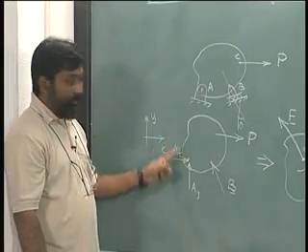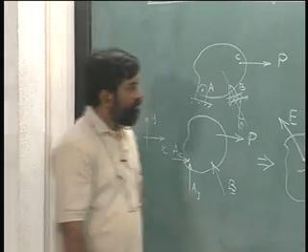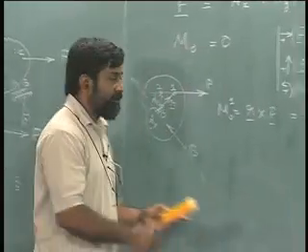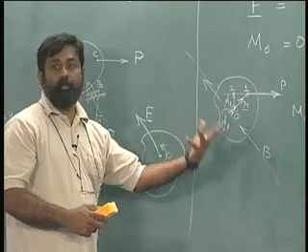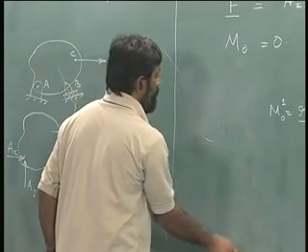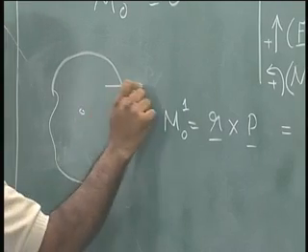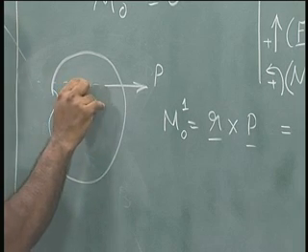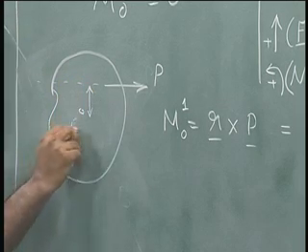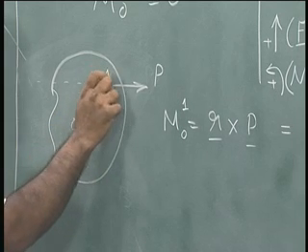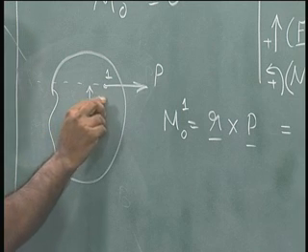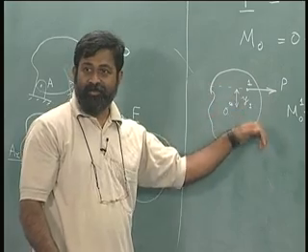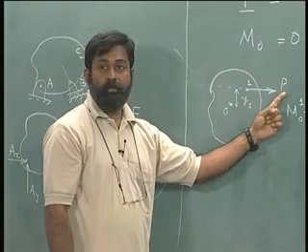And in a similar way here, it is simpler if I write it as Ax and Ay because of the distances that I can find out. I am just going to erase this and draw fresh so that you understand how easy it is if I write it in terms of components. So, if this is the body, if I take this force P, I know this is a horizontal force. All I need to do is to find out the vertical coordinate difference between this point O and this point 1, right, and this y coordinate of 1 with respect to O will immediately tell me that is the lever arm, or that is the arm that I have to use to multiply with the magnitude of P.